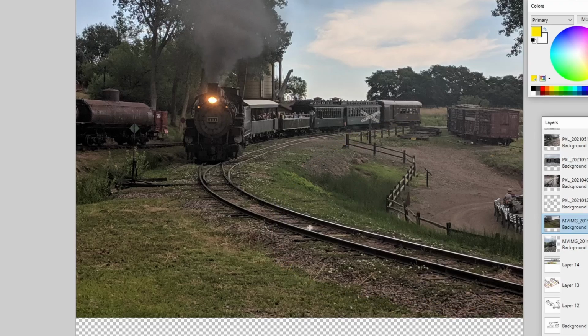These days, there are actual mechanical tampers that basically see the tie, and then they have lots of little vibrational little hammers that come in on either side. They do their thing, and it squishes down the ballast and vibrates it into place such that it can't move anymore. You've maybe seen these. They're on-track equipment, typically yellow on the railroad. They look very cool, but that's what they're doing, they're tamping the ballast down when they've got those little tendrils. It almost looks like an insect of some variety. But it's a really important thing to make sure that your track doesn't go anywhere.